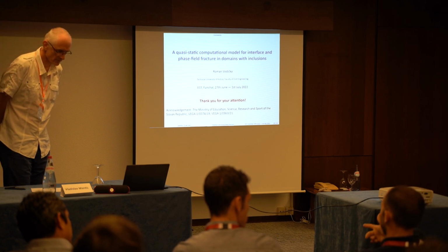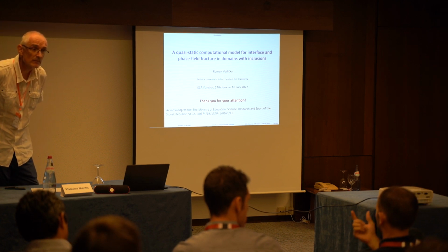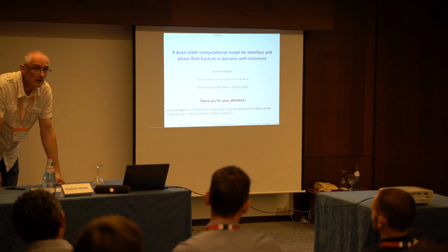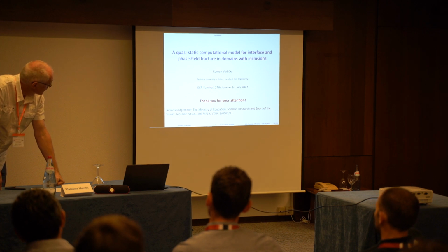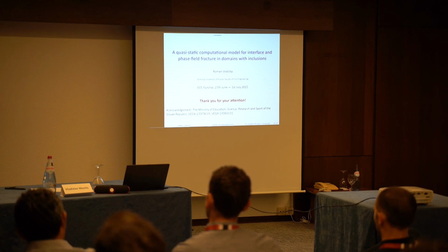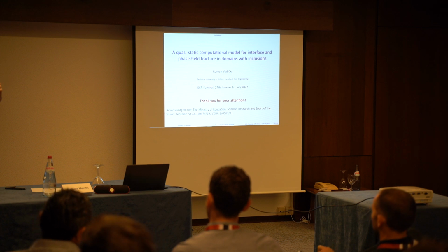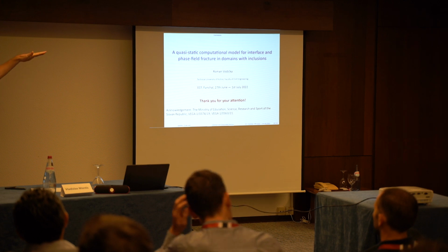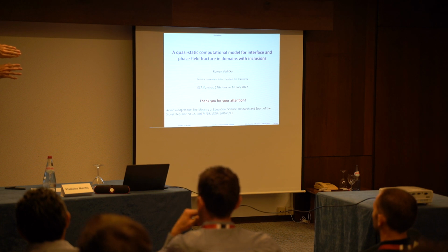Using the one length scale, you diffuse damage in a symmetrical way around the interface. Well, that may be similar or not, but as I said, the material of the inclusion which was used was rather stiffer, like for example steel reinforcement in concrete. So it has different material parameters. Nevertheless, in the case when there was the straight interface, the materials in both parts were the same.